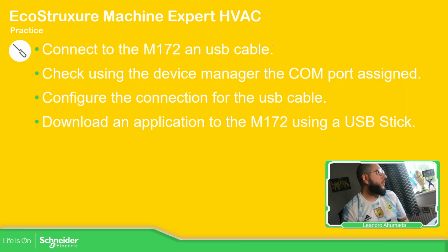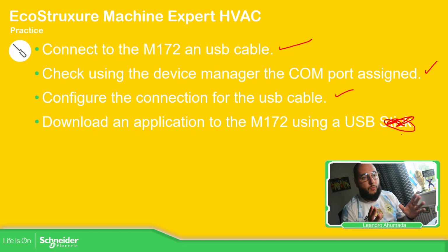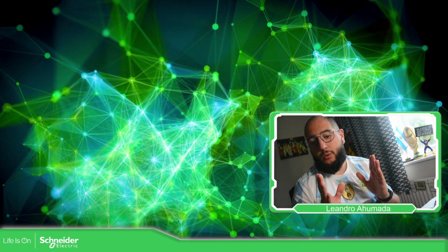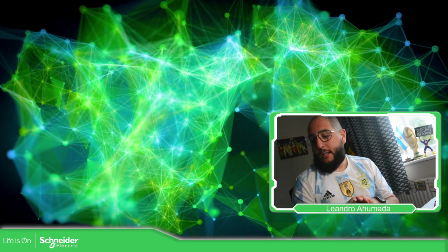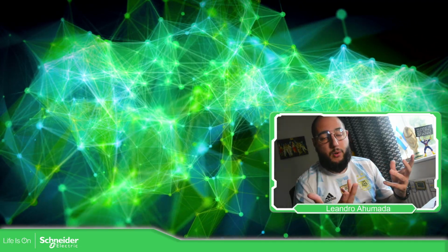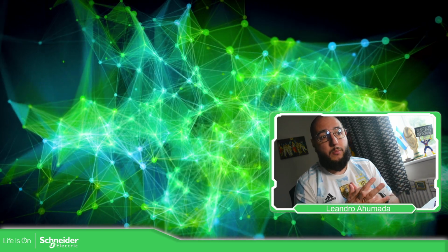So connect to the device, check the component side, configure the USB connection, and download using the USB cable. We have already done that. It's very simple, very straightforward. The important thing here is to use the right cable, data, power, or use one of the Schneider ones, then connect to the device, see that you have a COM port assigned, and use that COM port in the communication settings in order to connect using Modbus.